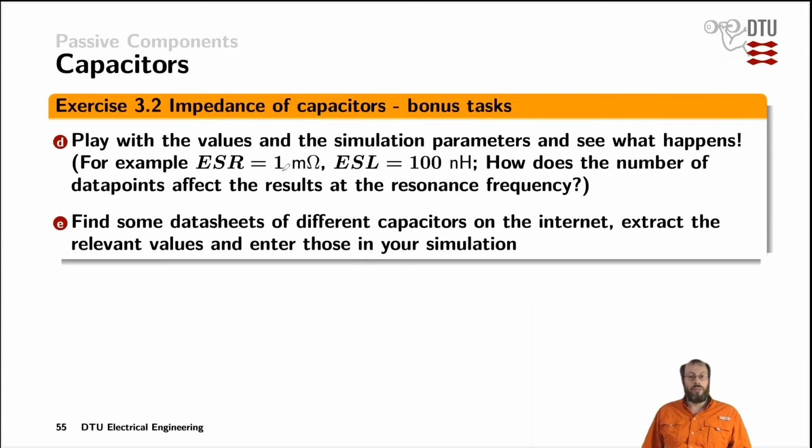If you fancy to do any extra exercises, you can start to play around with the given parasitic elements, the ESR, the equivalent series resistance. For example, you could turn it into a 1 milliohm or whatever you like. Just try different values and see what happens. And the same with the equivalent series inductance.